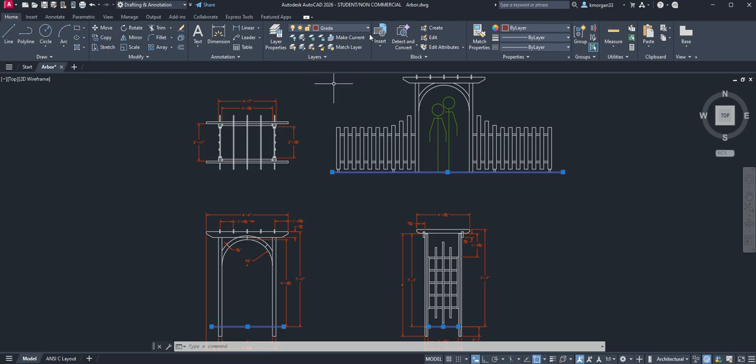So you have that many layers in this drawing. What we just did is put some of the objects on another layer. These objects were on the reference layer, and now we moved all of them by selecting them. As we selected this first line, second line, and then third line, we put them onto this layer. After we have changed the layer, go ahead and press Escape about 2 times. So now we're out of it. So see, the green color has now changed to color number 15. See all of this. Alright, go ahead and save it.